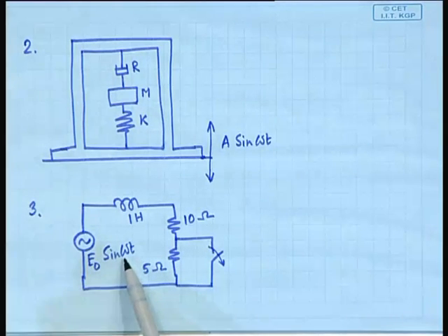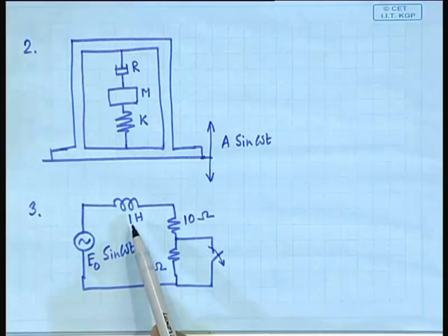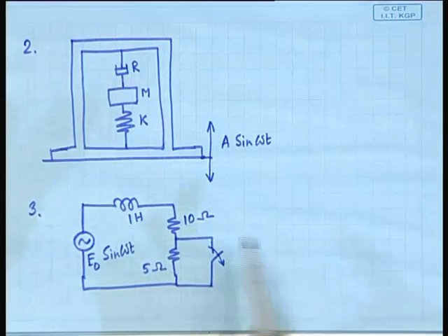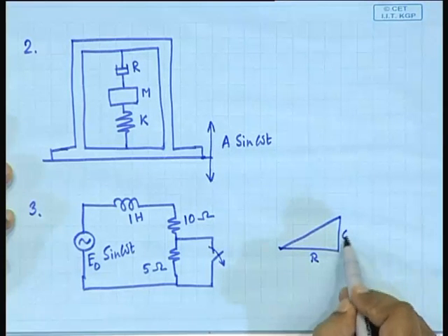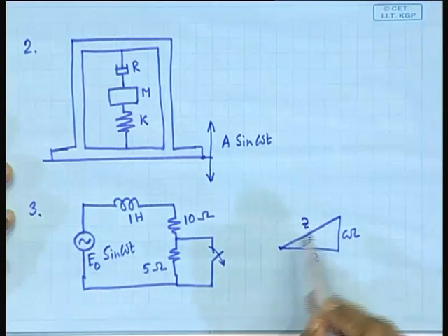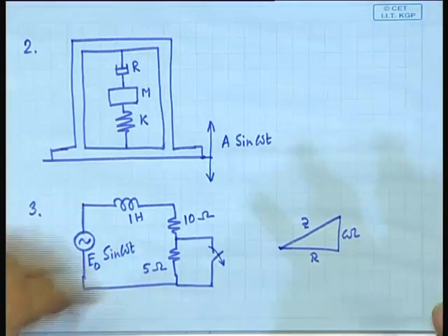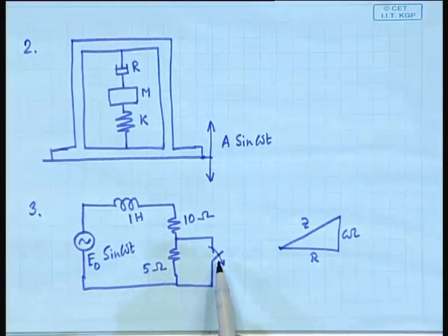Suppose the omega is 50, then it would be 2 pi f or omega L. So, the omega L will be the impedance of this one and the R, and you have to do it this way. So, this is R which is 10, this is omega L here. So, this Z, and then this E naught by Z sin omega t plus phase angle. So, that will be the current flowing when this was closed, and then at a specific time it was opened.